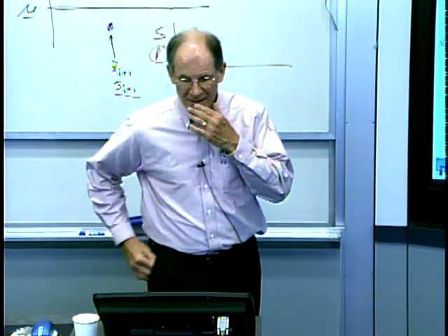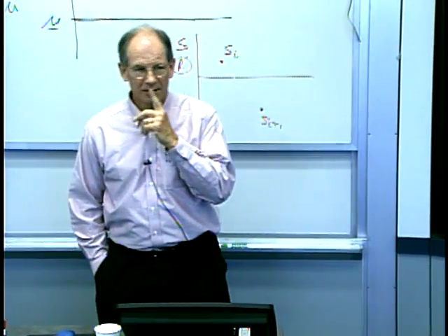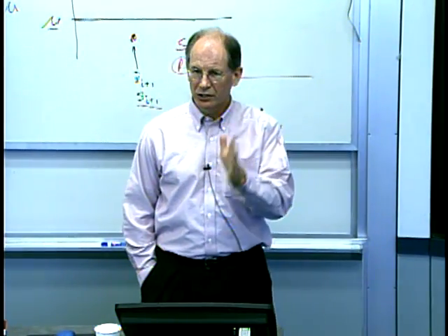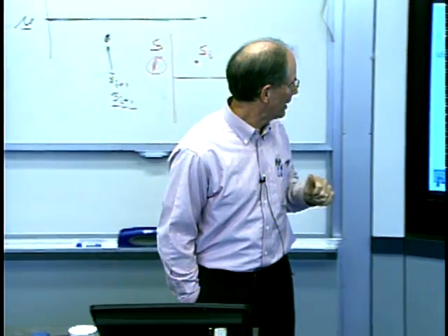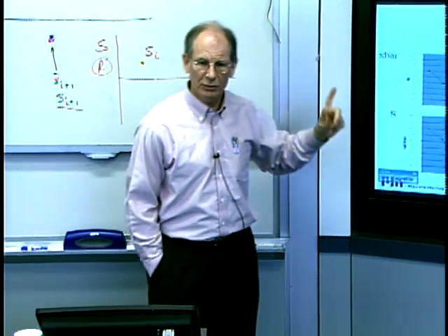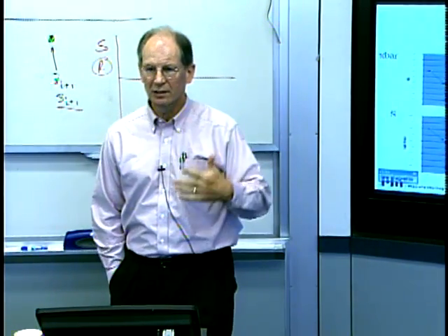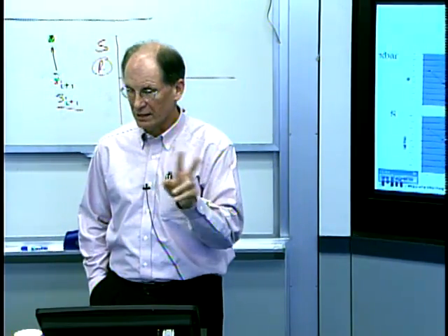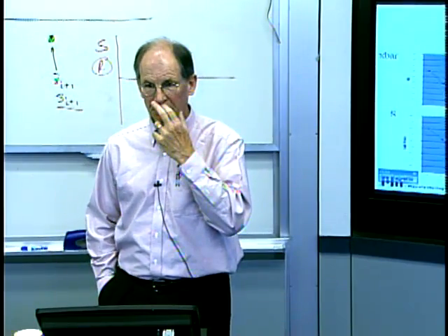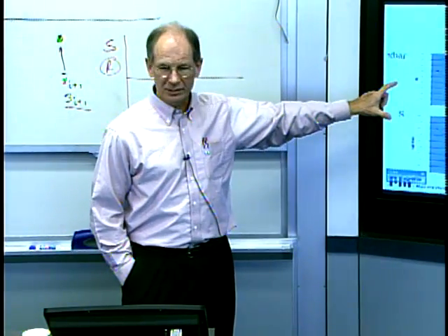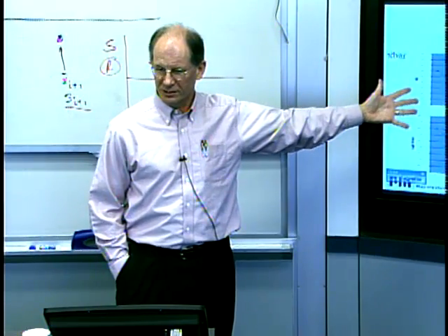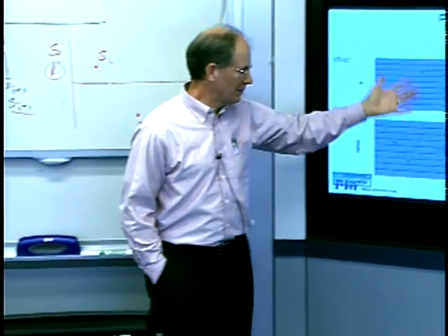Okay. So this is what you would actually see if you took measurements, grouped them, in this case, in groups of n, and plotted the data. This is what you would see if the process were governed by purely random, stationary, meaning fixed mean and variance, normal behavior. Because this was generated, in fact, in the PowerPoint that's on the website. I think you can click on this, and the Excel spreadsheet that generated it is there. So you can re-randomize it and see what happens.